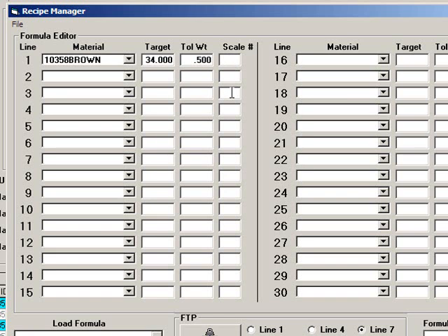Plus it can also be used to add in multiple. We've gone up to 6 scales total, which included two serial scales. They're not actually a scale in the IND780, but the multitasking of the IND780 allows us to use the serial port for a scale very easily.